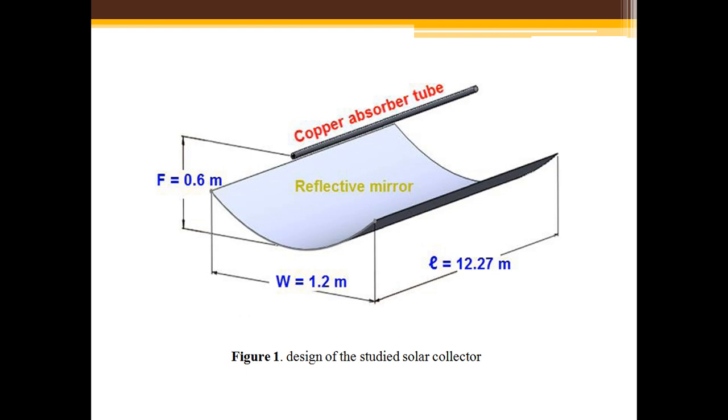The reflector of the parabolic form is one of the most important part of a studied parabolic trough collector. Its purpose is to concentrate direct normal solar irradiance in the focal line. Moreover, the reflector are mirrors that can have different shapes and can be made from different materials, depends on the configuration chosen by the exploiter.